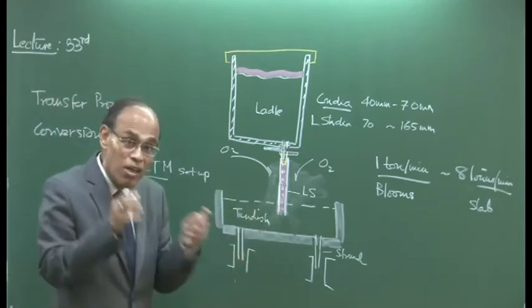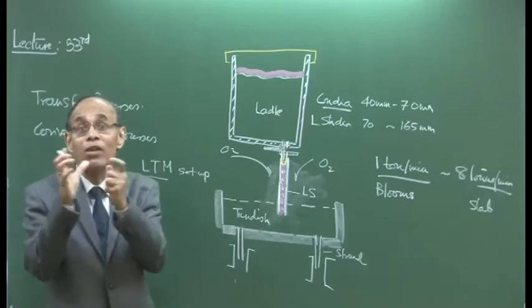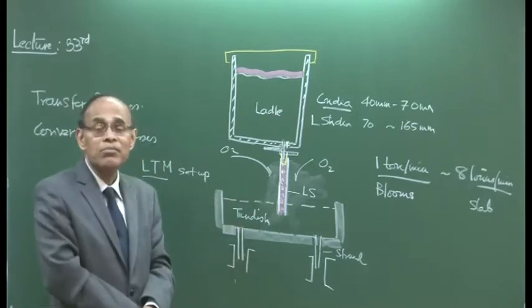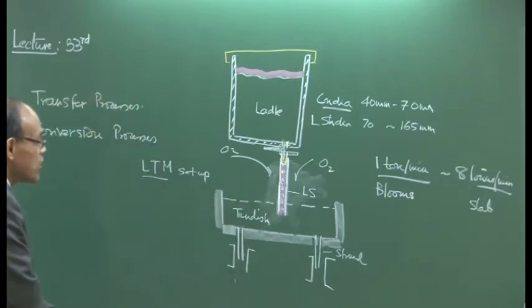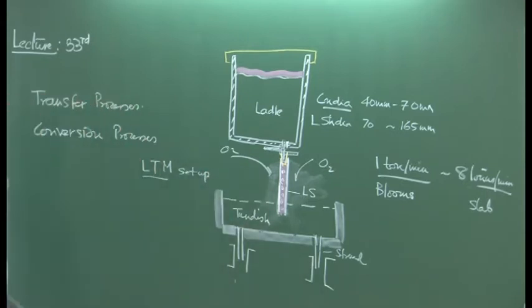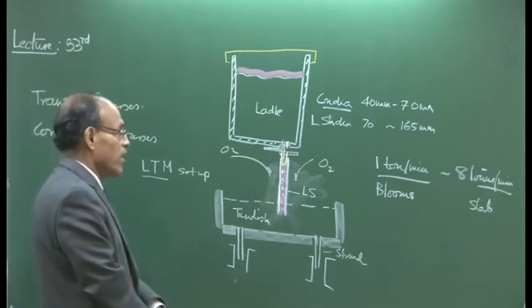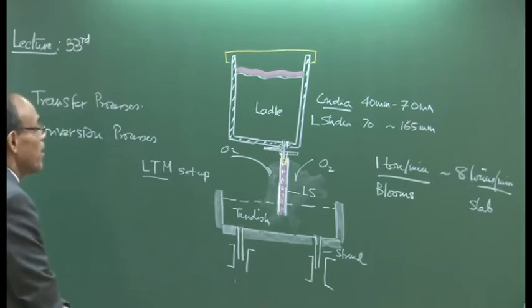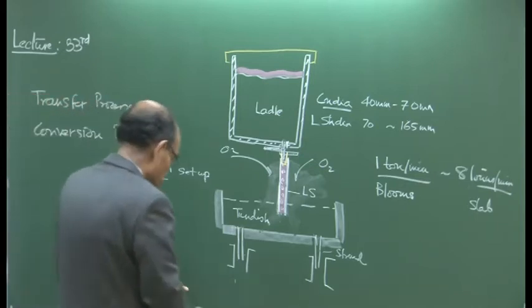It contains dissolved aluminum, which is just waiting for every opportunity to react with oxygen, and a little bit of oxygen going into the melt can lead to a significant amount of reoxidation, and that needs to be prevented at any cost or minimized to the extent possible.